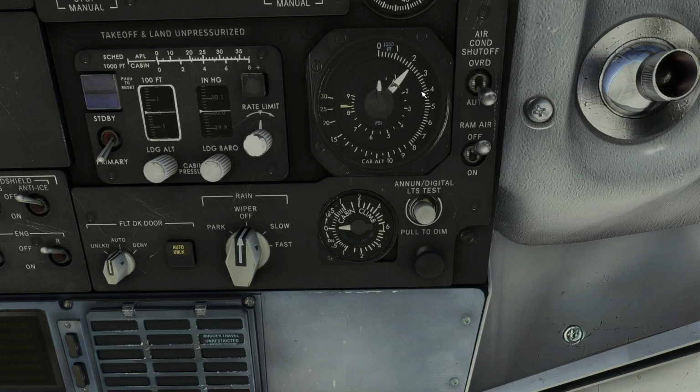And it's very bad. So the system is designed, if the cabin altitude climbs above 10,000, you will get a cabin altitude alarm, and that will go off when the cabin goes back below 10,000 feet. So generally speaking, you want to see the cabin altitude probably no more than 8,000 feet, somewhere between 7,000 and 8,000 feet at the maximum, and your differential should never go beyond this bug over here. The ideal differential, I believe, is 7.77 according to the manual, but it can go up a little bit higher if it must. Again, you're going to have issues if you try to climb above the service ceiling of 37,000 feet, so don't do that. Otherwise, you have problems, and you'll get alarms and things like that.